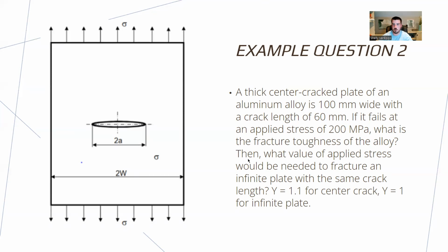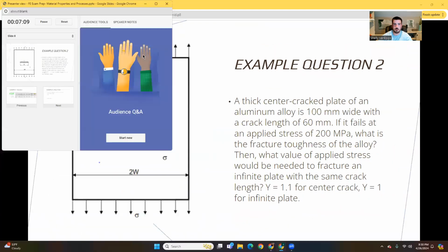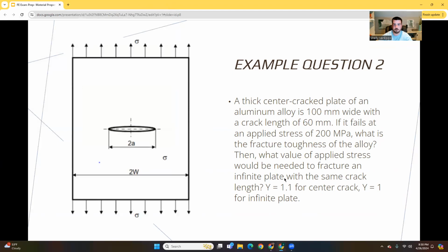But the second part of the question says, what value of applied stress would be needed to fracture an infinite plate with the same crack length? Our Y value for this is given: 1.1 for a center crack, and Y equals 1 for an infinite plate.